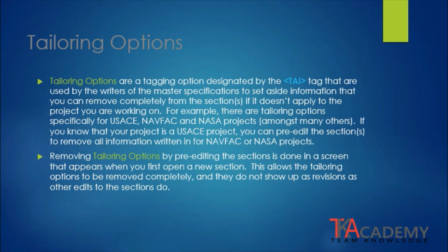If you know that your project is a U.S. Army Corps of Engineers project, you can pre-edit the section to remove all information pertaining to NAVFAC or NASA. Removing the tailoring options by pre-editing the sections is done in a screen that appears when you first open a new section for editing. This allows the tailoring options to be removed completely and they do not show up as revisions or other edits to the sections.